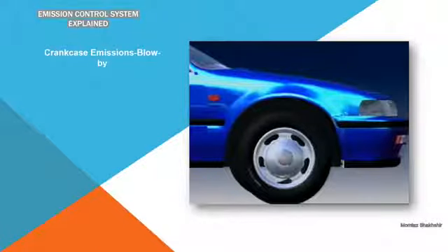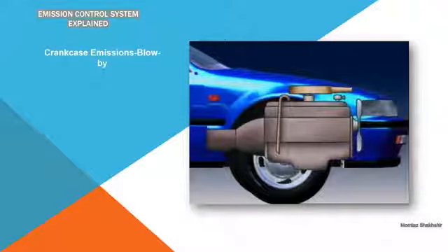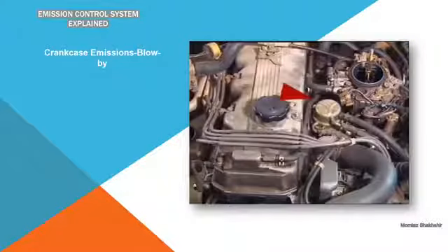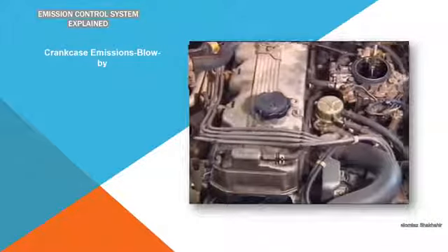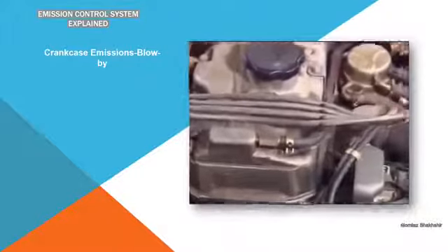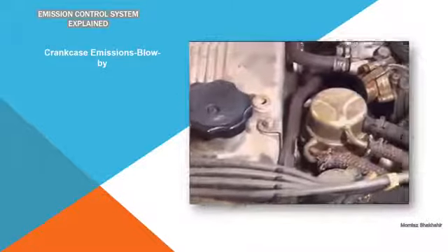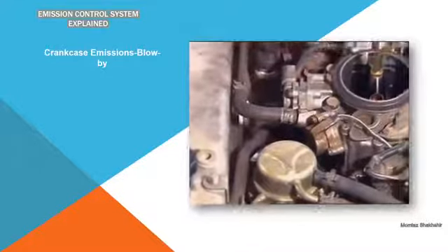In older vehicles, crankcase vapors were vented directly to the atmosphere through a breather tube or road draft tube. It was shaped to help draw the vapors from the crankcase as the vehicle was being driven. Modern vehicles are required to direct crankcase breather gases and vapors back into the inlet system to be burned. A common method of doing this is called positive crankcase ventilation, or PCV.